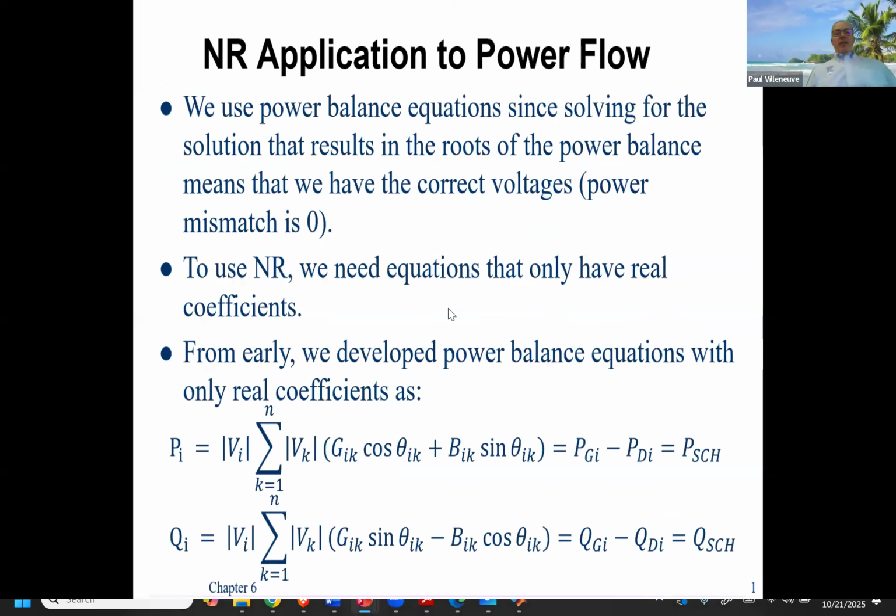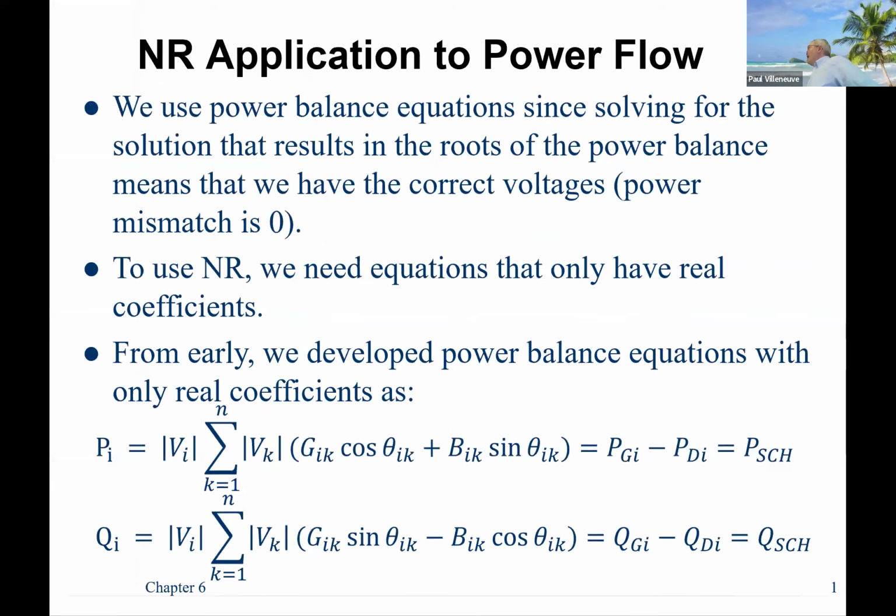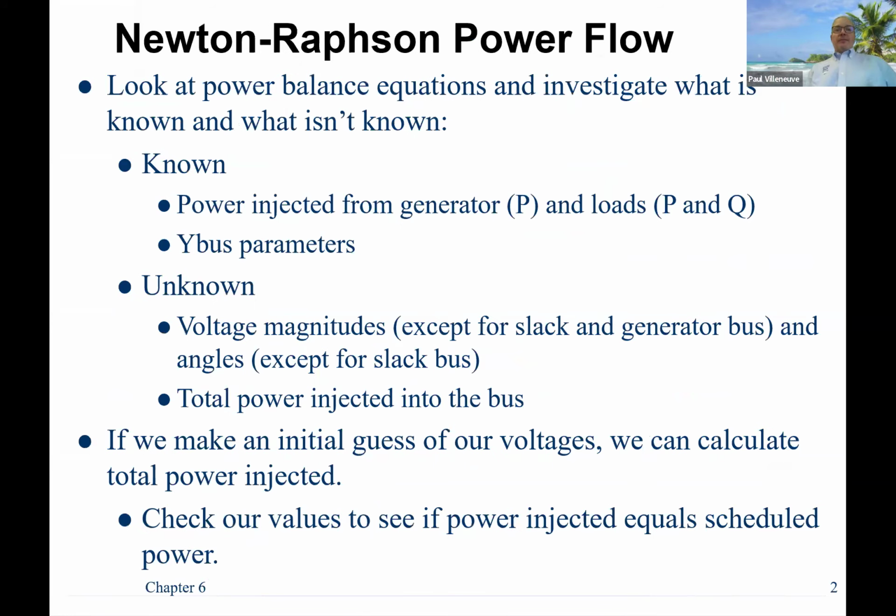Okay, so here are our real power and reactive power equations broken up so that you don't have any complex numbers. So we just developed those. We've already specified slack, gen, or load bus, so we can come up with power balance equations, and we can also come up with the unknown variables that we need to solve for.